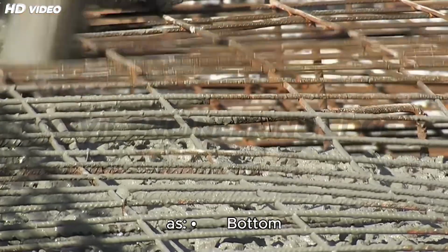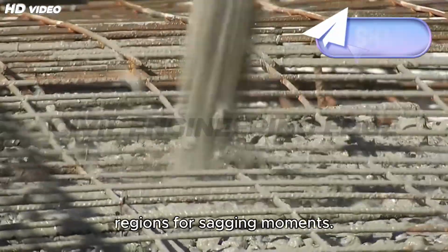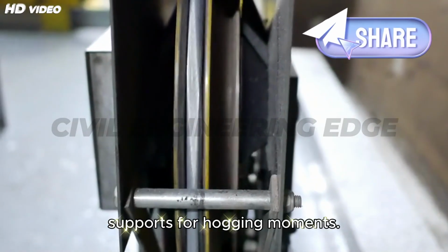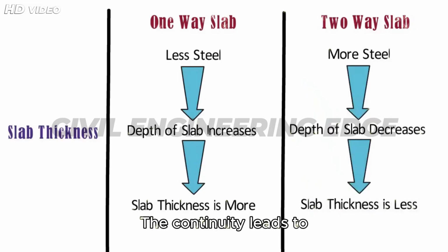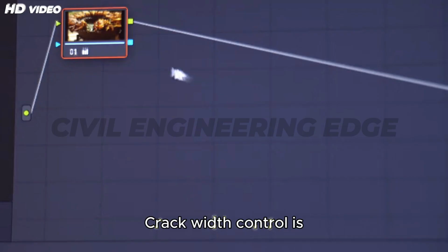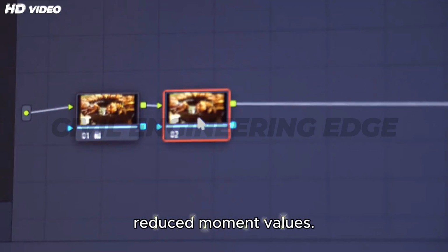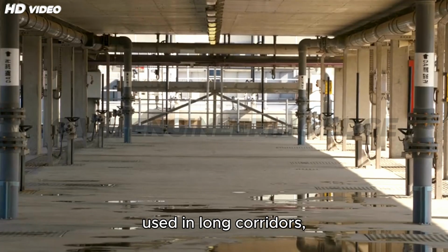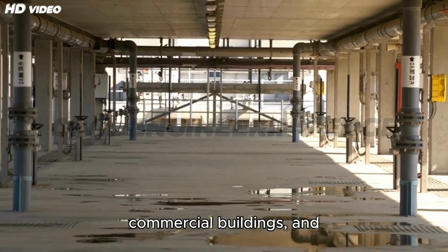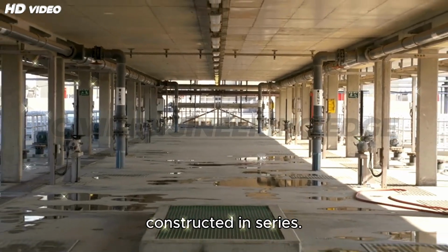Reinforcement is placed as bottom steel in mid-span regions for sagging moments, top steel over supports for hogging moments. The continuity leads to better load sharing and serviceability. Crack width control is also improved due to reduced moment values. These slabs are widely used in long corridors, commercial buildings, and parking structures where multiple bays are constructed in series.